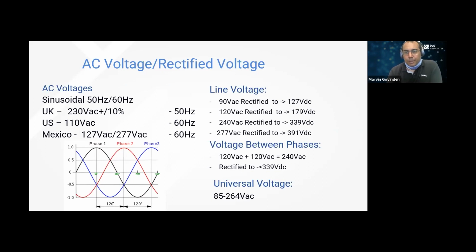So all our components that will go into our circuits have to tolerate that voltage and voltage spikes in DC. So that could increase maybe 3 to 5 times on those lines. So depending on our circuitry, we need to protect those with the correct components. And also that changes as you get to higher voltages and we start tapping off 2 phases and getting really high voltages.